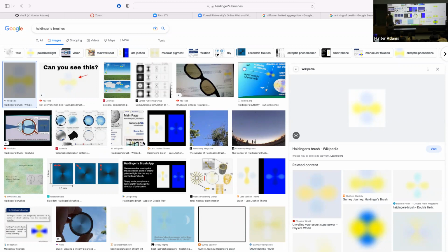It's awesome. So anyway, the whole sensory augmentation direction is an interesting place to go with final projects. A whole different flavor of project: right now, we program the RP2040 by holding down the button and drag and dropping the program over, and it ends up going into external flash memory. Could you build a bootloader that would allow us to program the board through light, so that we could flash light at some light sensor and reprogram the device just by flashing light at it?